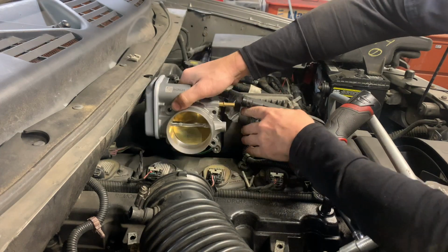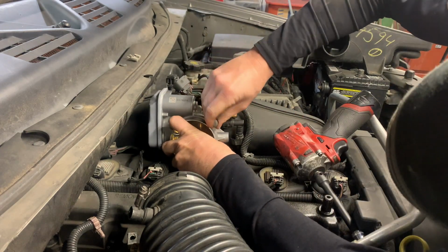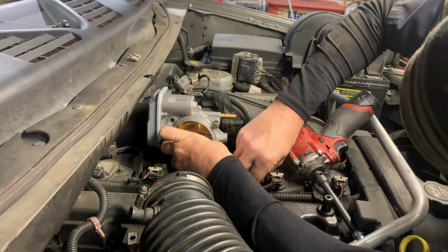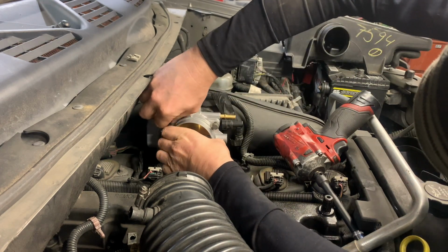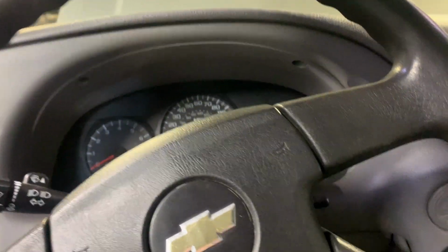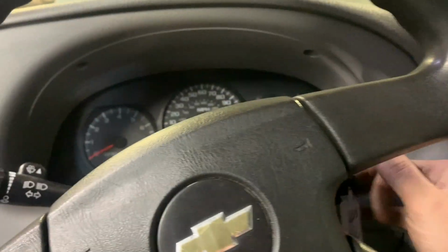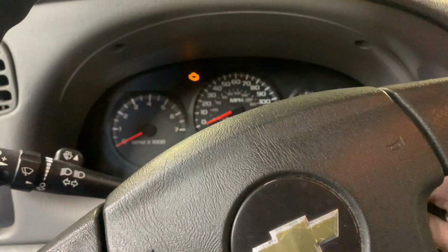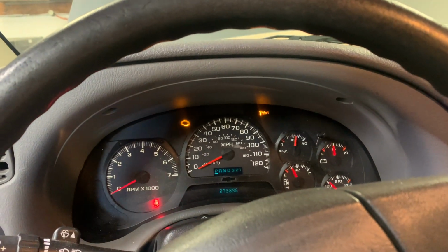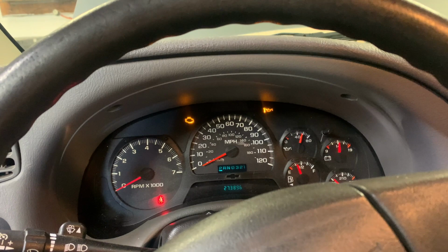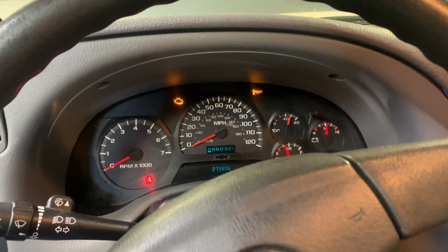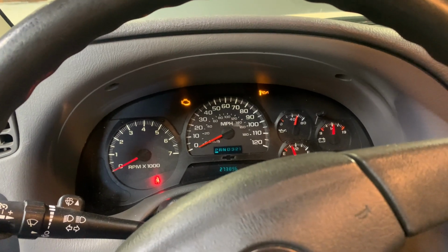Here I'm just putting on the new throttle body. No big deal, just 4 screws. Plug up a connector and put all your breather hoses back together. And here we are. I'm getting in the car and I'm starting it up. I basically test everything out, rev it up. Before, I couldn't even give it the throttle and it'd go right into limp mode, right when it detected. I couldn't even pull out of the drive. And everything is working great, guys.